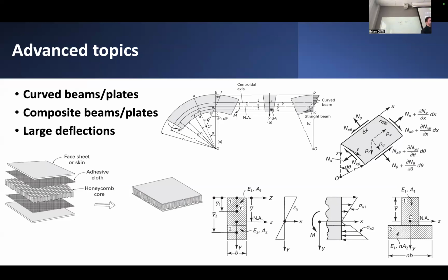Sometimes that's fine, and sometimes that's not so fine. But it usually means that if you're really trying to capture that curvature, you have to use either specialized curved element formulations, or a lot of smaller subsegments to capture that initial curvature. So just be a little bit careful of that.